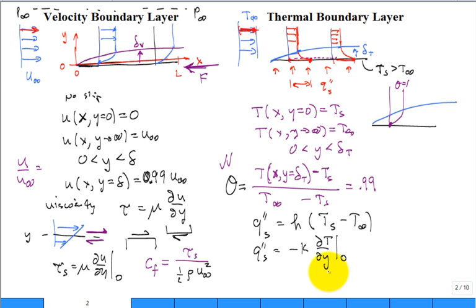But it's parallel to this for the viscosity. It says shear stress at the surface. Oh, I need the slope. What is the gradient of the velocity profile at the surface? Same thing for the heat flux. It is diffusing through heat diffusion, just like linear momentum was diffusing through the momentum. This is diffusing through the thermal conductivity. You have the diffusion of heat.